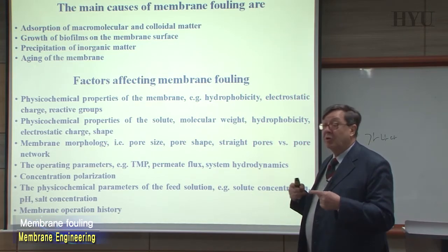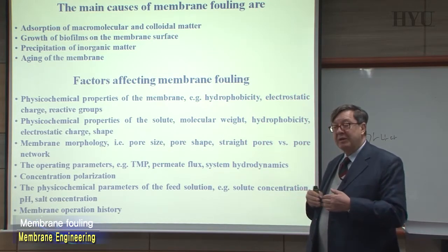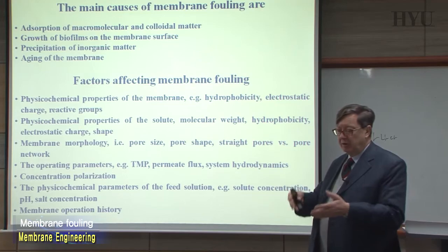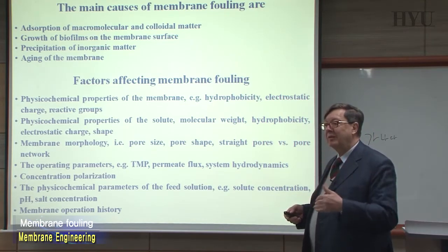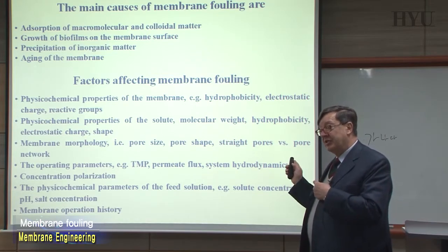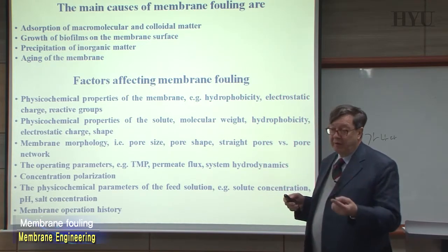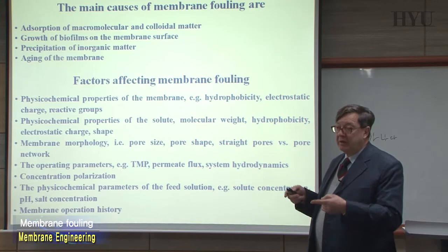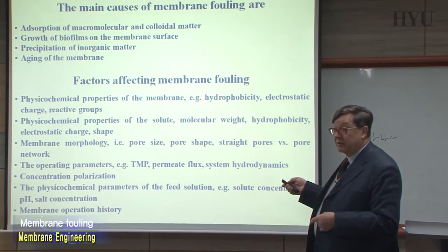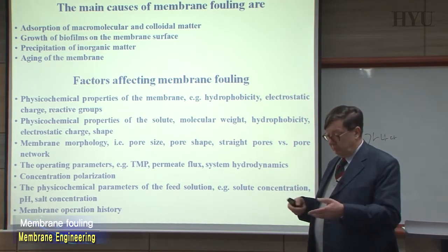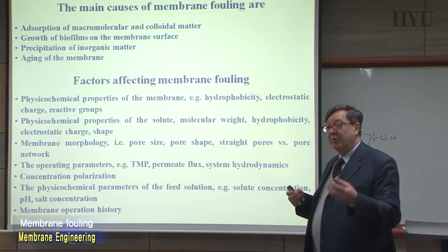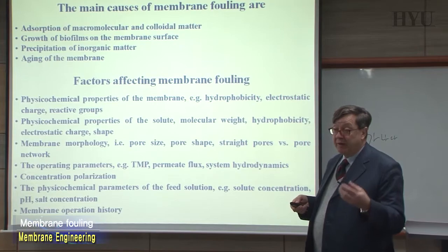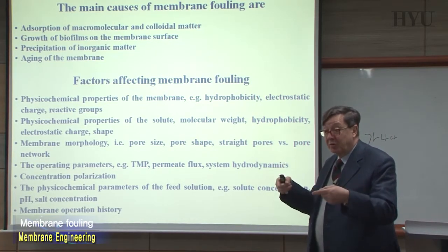Biofouling is a little bit more complicated. Normally it appears after a long time. It does not appear in a few days or hours. It appears after 6 months or 1 year. And we will understand why. Because biofouling is fouling related to the formation of biofilms, and these biofilms take time to be formed, and the real effect is not the presence of some biofilms, it's the presence of the products of biofilms.